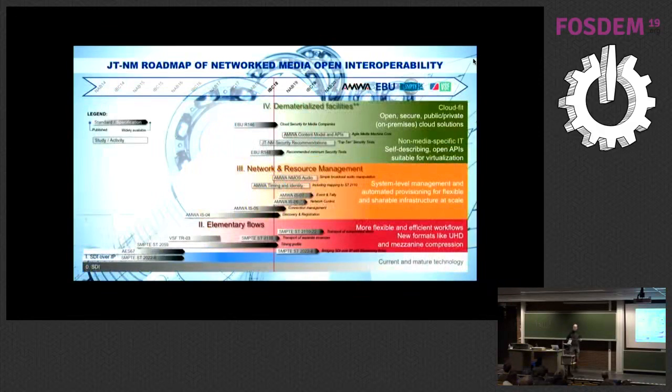Now, to give you a little bit of insight on the industry, this is a very interesting roadmap. Who has seen this before? That's very good, right on track. So this is our SDI technology, and we wanted to move to IP. A few years ago, they said, let's take all the SDI, wrap it into IP, and transport it. But actually, that's not what we need to do, because SDI is encapsulated with audio, video, and ancillary data. So if you just do that, that's a waste of bandwidth in a video plant, because you need to de-embed and embed all the time all the ancillary data and the audio.